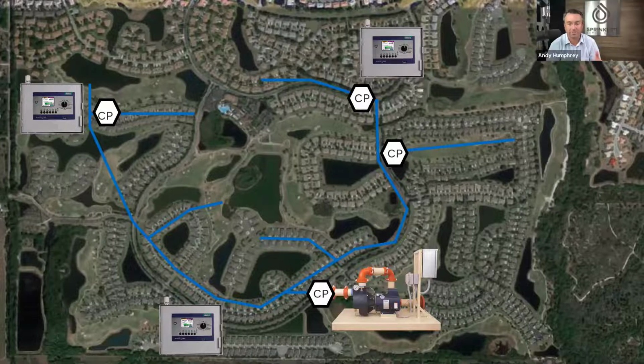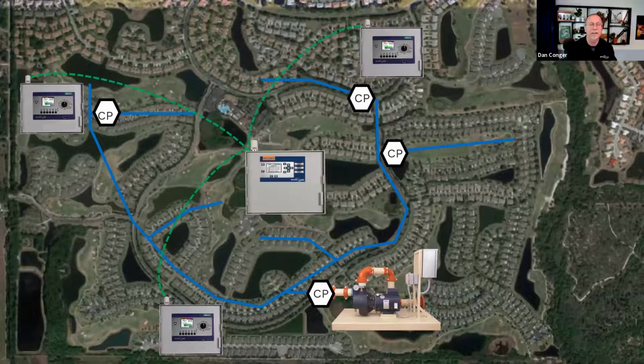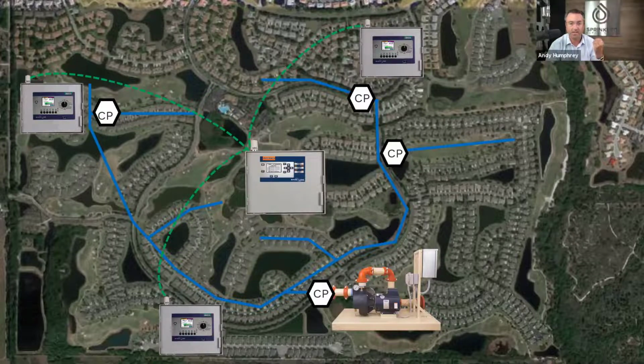Now, remember, we're talking about the functionality of the FlowStation. That's the key here, not the 3200 controller. Yes, it's there, but it's really the functionality of the FlowStation that allows this to happen. So if you had a singular controller and you wanted this, you need a FlowStation. The only way we're going to get those multiple control points to work is when we have a FlowStation and we allow it to communicate and share that data. Even with a single controller, only the FlowStation has the algorithm to do the submain line capability that we're talking about.